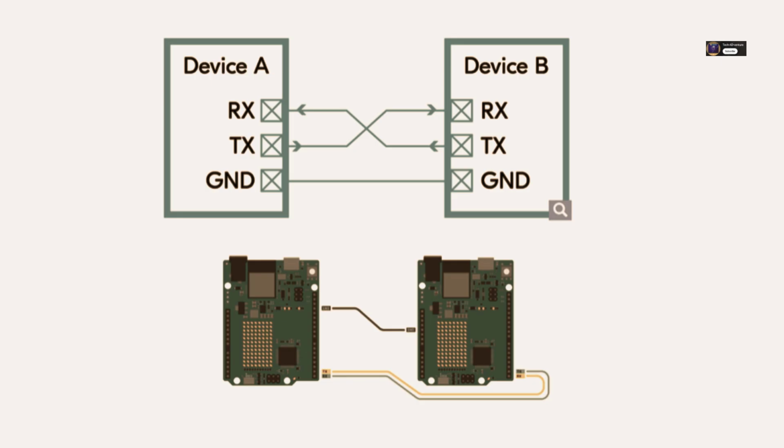Disconnect anything else from your microcontroller's UART TX and RX pins, and connect the TX pin directly to the RX pin on the same chip. Then write firmware to send some data out the TX pin and immediately try to receive it back on the RX pin. If you receive exactly what you sent, you know the UART peripheral itself, and your basic send-receive code, is likely working. Ah, clever.